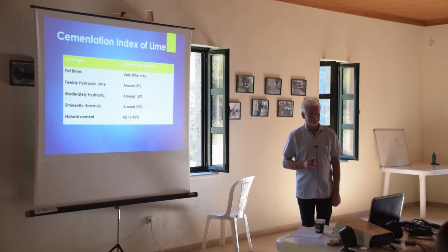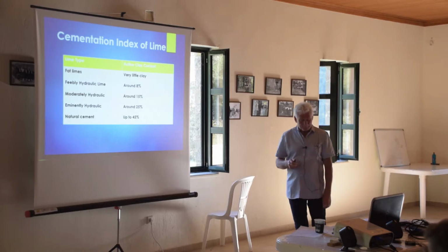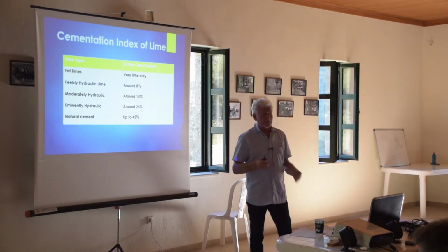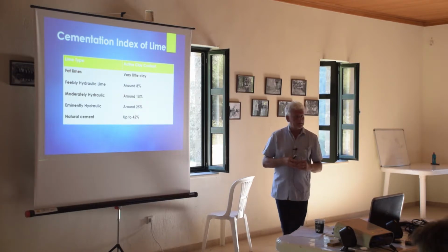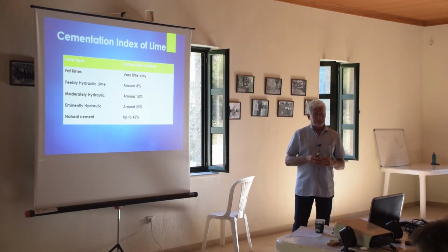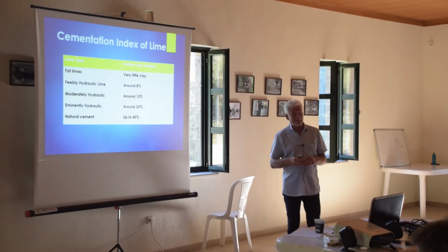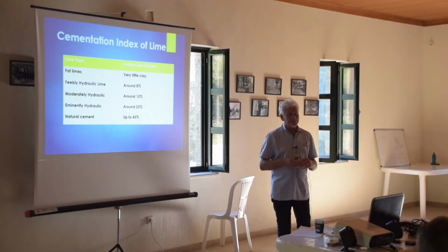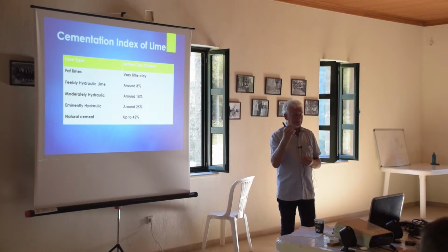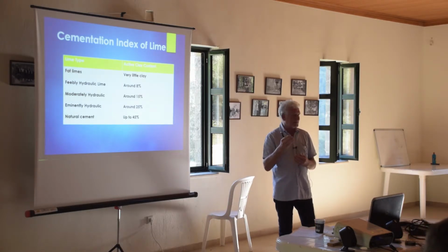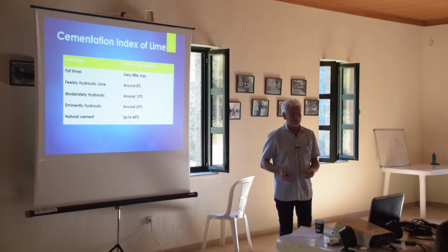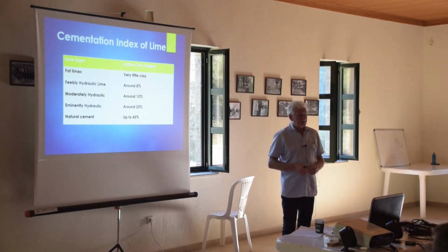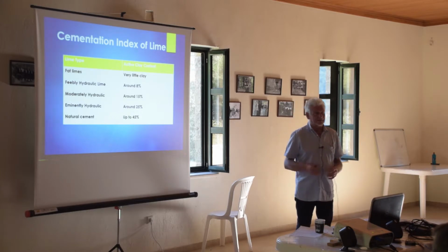Why is it bad that it sets too fast? It was stronger than the painting material itself. Yes, the actual structure was in very, very soft clay bricks. It was an old structure from about 1750, and it was clear that if we left it on, and there were going to be any problems with it, let's say it fractured in the future, and rain got in behind it, it was going to destroy the bricks anyway. So we decided to accept that we made a mistake and did it again.